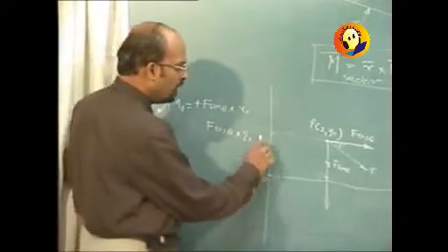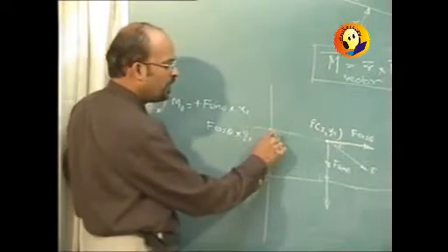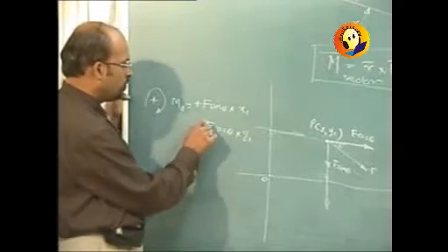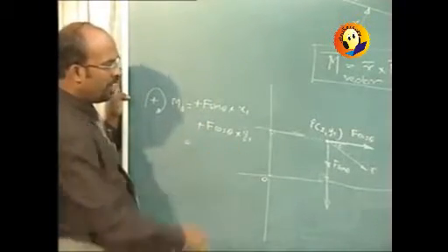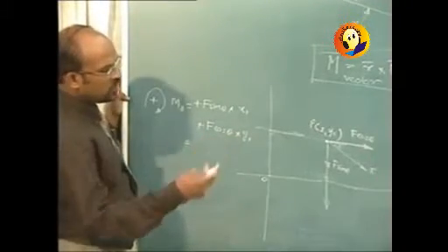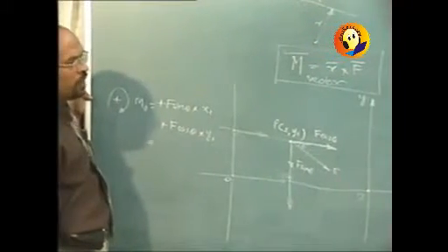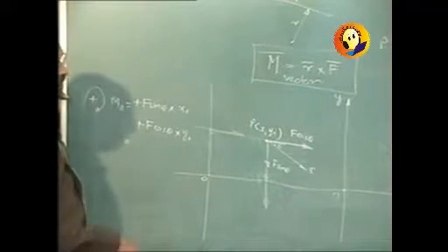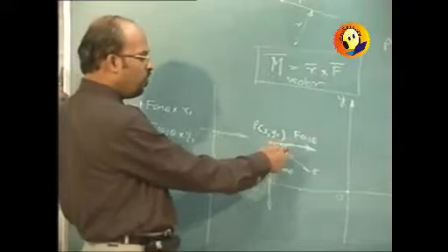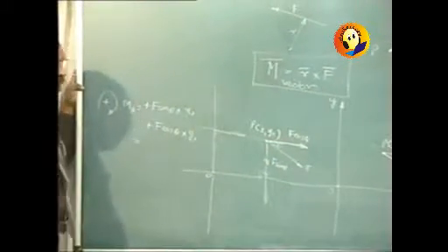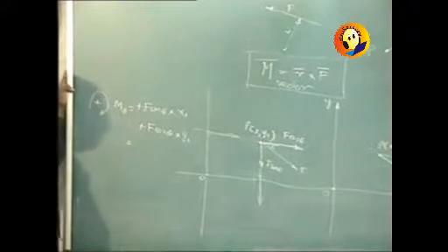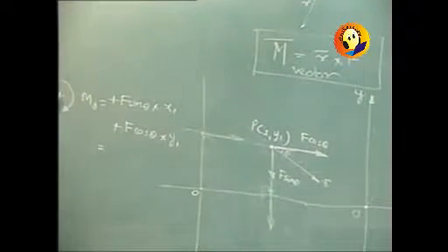Similarly over here, if you move along the perpendicular line and then along the force, it is going to give us again a clockwise moment. This will come out to be entirely a clockwise moment about the origin. So though the definition of the moment is force into perpendicular distance, probably we will deal with it in a simpler manner because we can divide that force into components, and it is a horizontal force into vertical distance and a vertical force into horizontal distance. That should be the criteria.